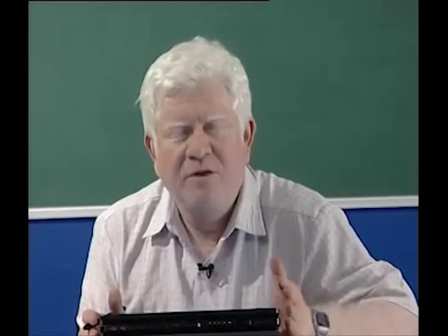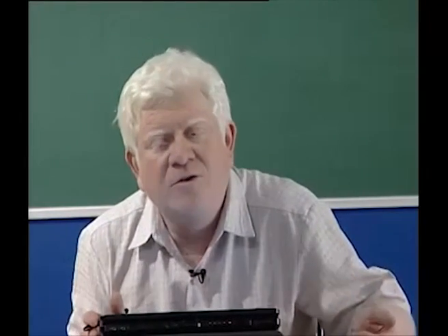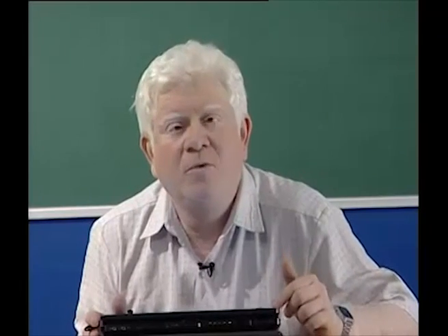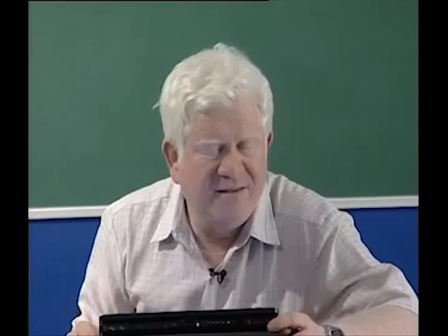But now that we have a new case where the input is applied at tau instead of 0, given that the earlier initial condition or auxiliary condition was specified at t0, where should we specify it now? This is where we should be careful in generalizing properly from the previous piece of information we got. Earlier we said instead of Vc of 0, we now specify Vc of tau.